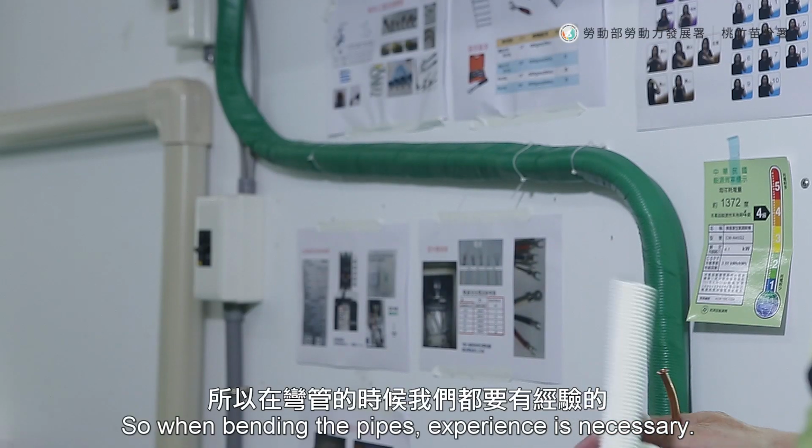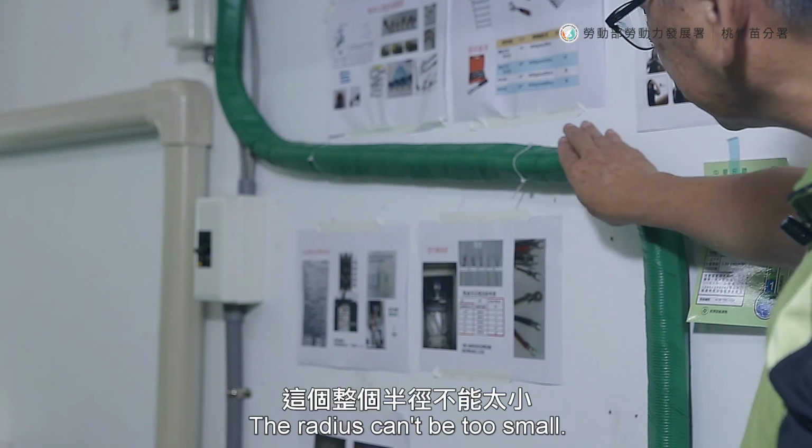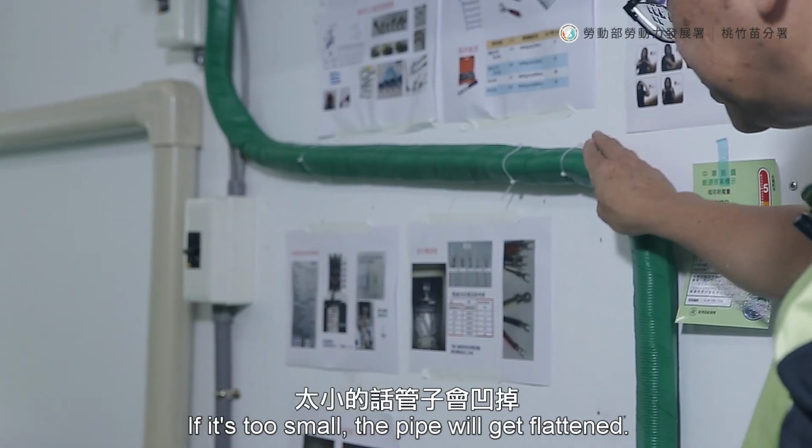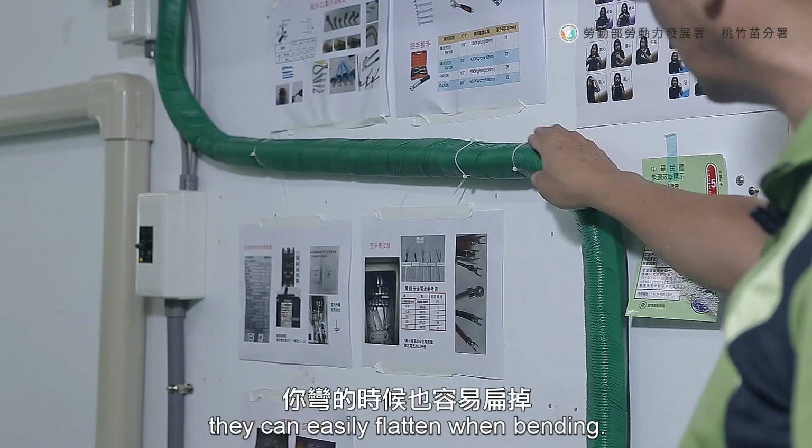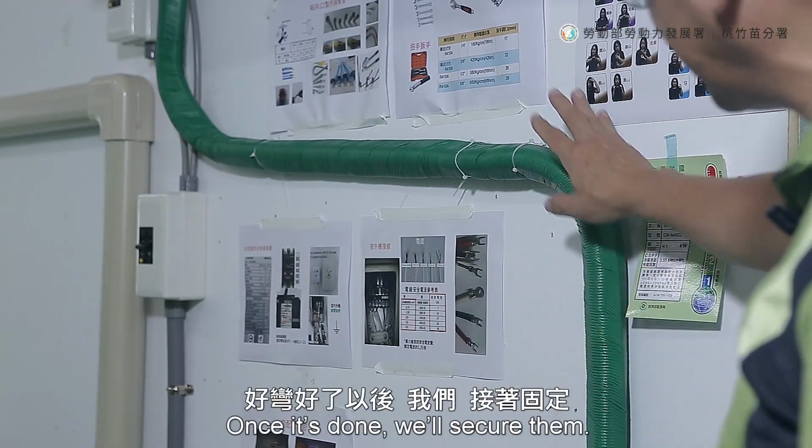So when bending the pipes, experience is necessary. The radius can't be too small. If it's too small, the pipe will get flattened. Also, the quality of these copper pipes can be poor. If they're too thin, they can easily flatten when bending. Okay, once it's done, we'll secure them.